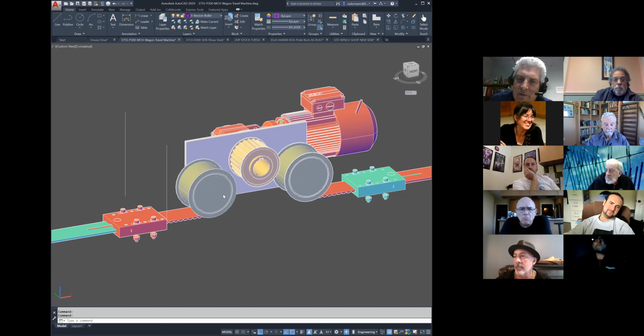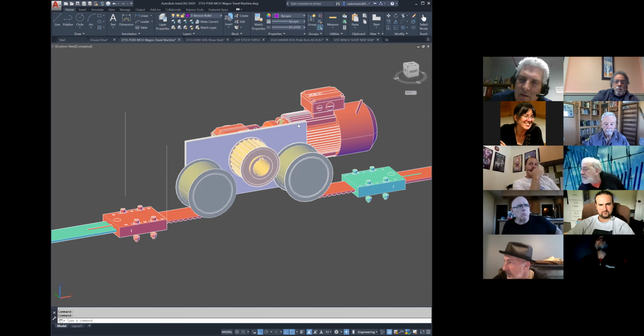These are just idlers. And what we end up with is a piece of belt that is anchored to the stage floor at its ends. And then, kind of like an old film loop projector, this belt loops up in and through this machine and then back to the dead end. And the machine is moving back and forth on this fixed piece of belt, so it can pull itself from end to end.